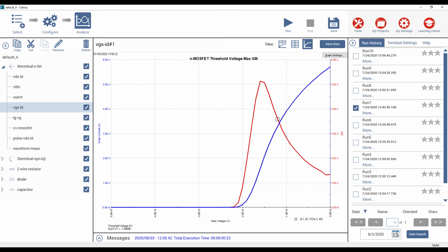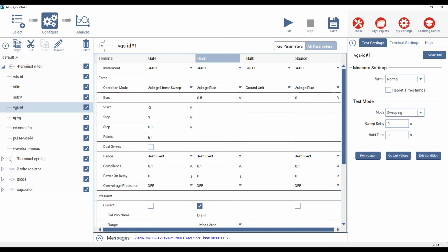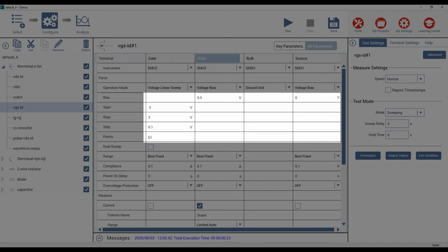Many of these measurements can be done directly with the semiconductor parameter analyzer without having to adjust or move to other types of equipment. Now I'm going to go and adjust the probe station and take it from probing a depletion mode device to probing an enhancement mode device, since enhancement mode devices are favorable for power device applications. The probe station has now been adjusted from probing a depletion mode device that we looked at a moment ago to now measuring an enhancement mode device.